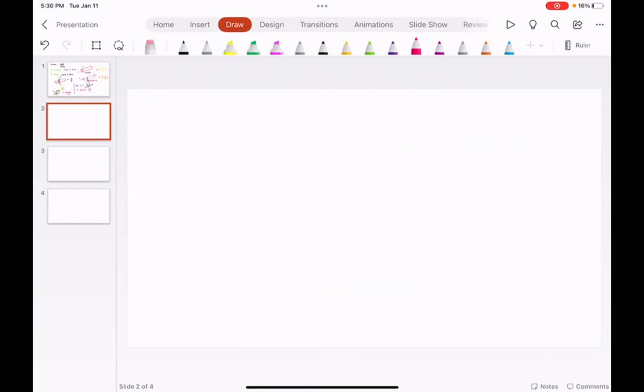What is the logic? If something has failed, it means some stress exceeded the material's built-in capacity, or built-in strength, if I use the right word. Now, what happens at 45 degrees? That plane is the weakest plane for aluminum. What do I mean by weakest plane?